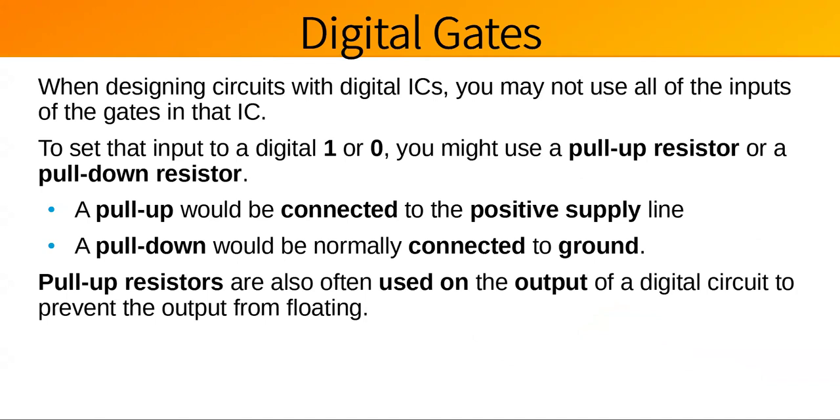If you don't use all of them, you don't want them floating around with noise and turning on and off, because that affects power and generates noise in the circuit. So you use pull up or pull down resistors to essentially tie the input high or tie it low, it doesn't really matter. Okay, so that it doesn't change.